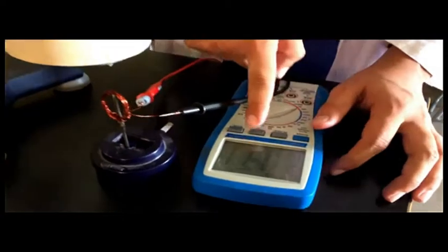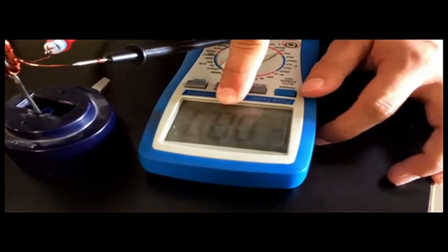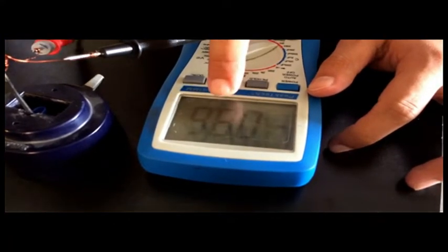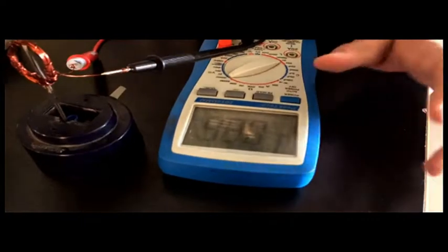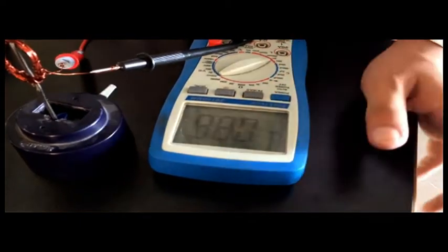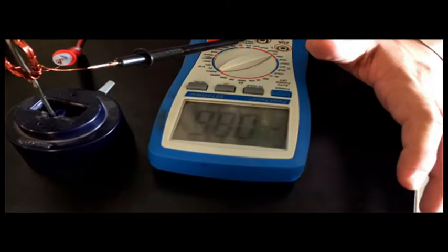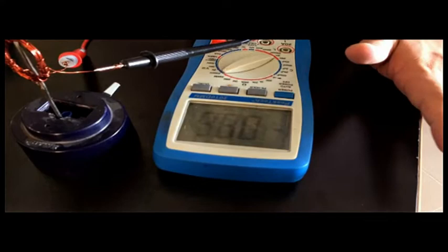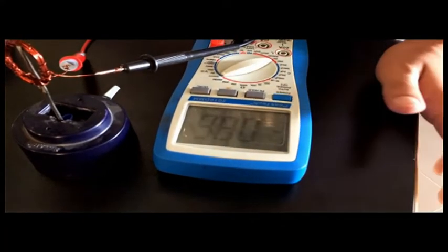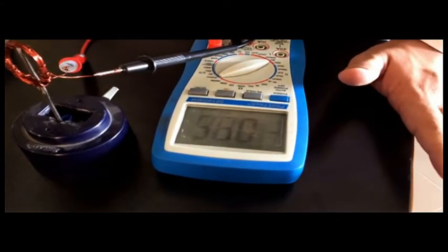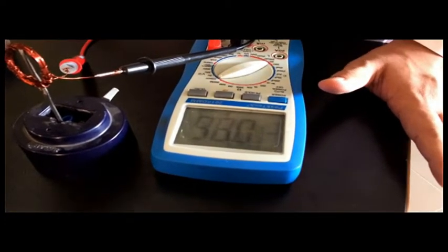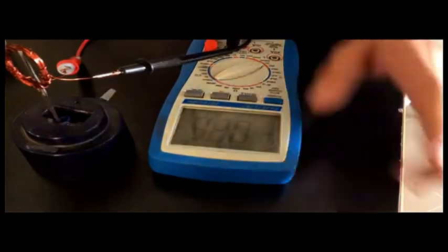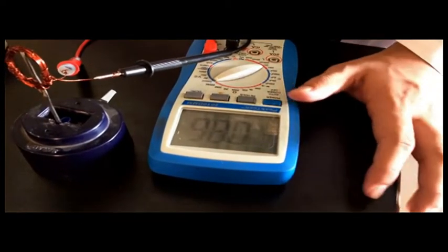After attaching the voltmeter, you can see here these are stray voltages. So you have to wait for this value to stabilize first. When we get our readings, we shall subtract this value from our reading, and in this way we will get our required accurate value. These stray voltages are perhaps due to the magnetism in our surroundings. As you can see, there are many wires going around in the lab for electricity and for other purposes. So these voltages are due to those stray magnetic fields.